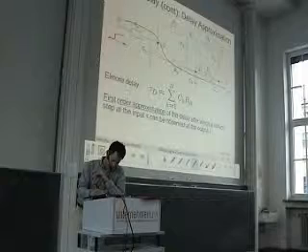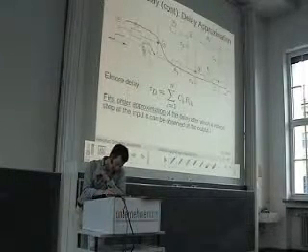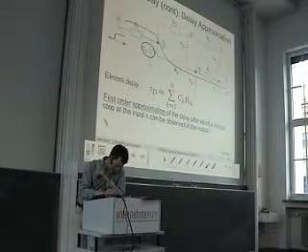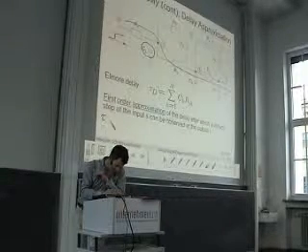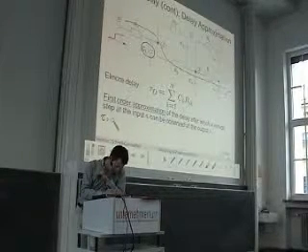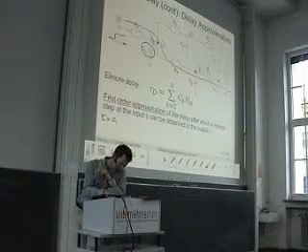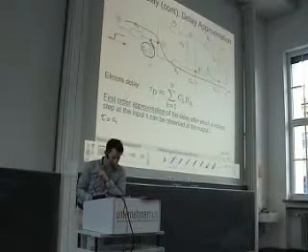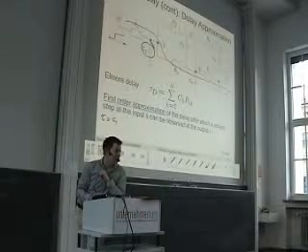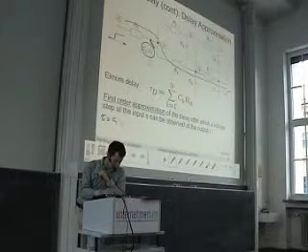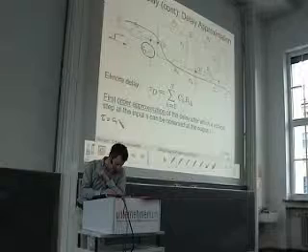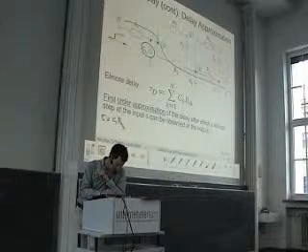First we look at this cap. Our tau is given by C1, and the resistor from this node to the input that is common to the red path is only R1, so we have C1 times R1.